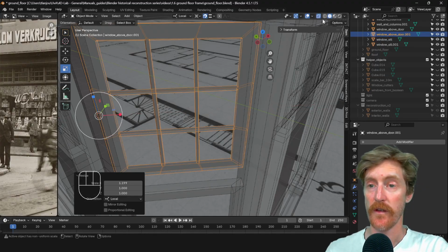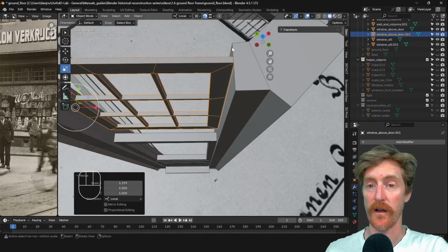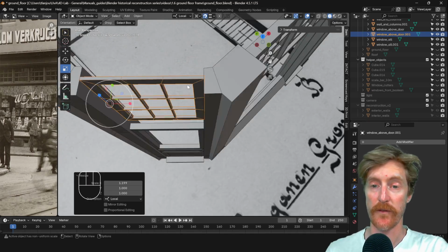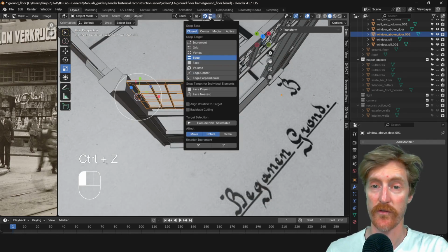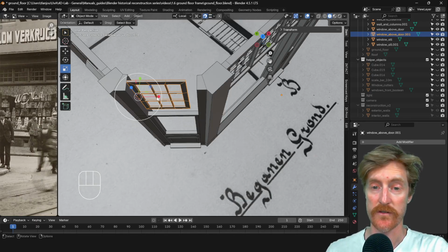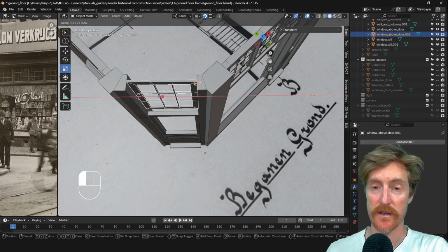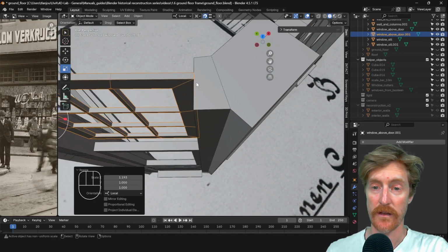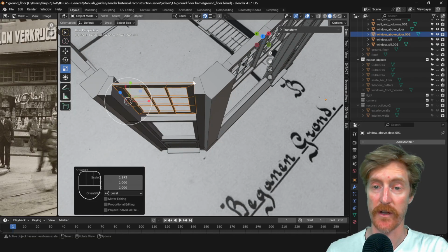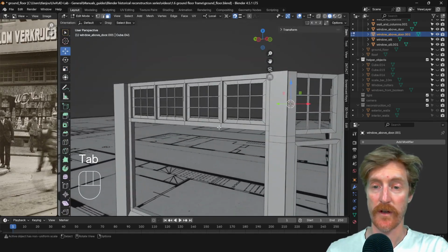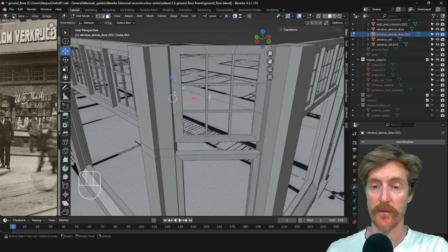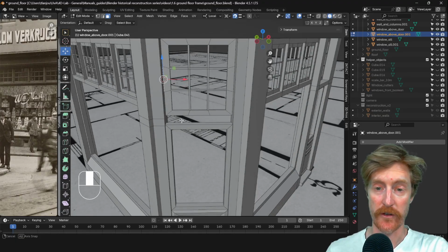like this, of course I want to exactly align this with that face. How do I do that? I need to turn on snapping. Edge snapping is fine, but also affect scaling. So when we now scale this, it properly aligns. So we have now quickly scaled up this window for reuse over here.